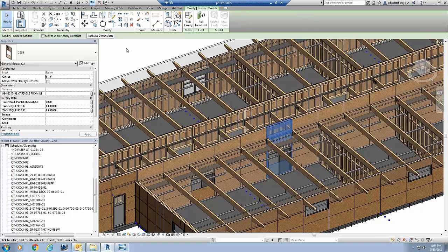We've also gotten into some areas where we don't configure a building, where I get a model that just has a window in it, and from the window I can panelize around it and make assumptions at certain lengths, because I can pull information from Dynamo on start points and end points of walls. With the way I'm now able to extract information from the model and get accurate locations of elements, it just keeps getting better and better. That's why I made the disclaimer before: we skipped 16 to come to 17, and 17 with global parameters is a game changer for Revit in general. You can do a little bit of everything.